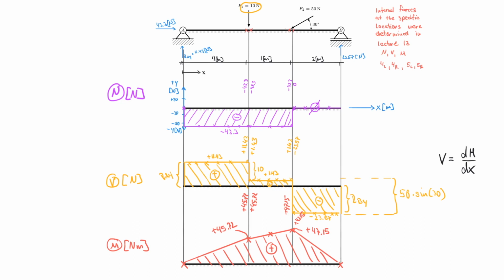But please memorize this one here, right? That the shear force passes through 0 where the moment is maximum, right? If you have done derivatives in the past, and you did if you are in this class, then you know that the function that goes through 0, that is the derivative, reveals where the parent function actually has a maximum.